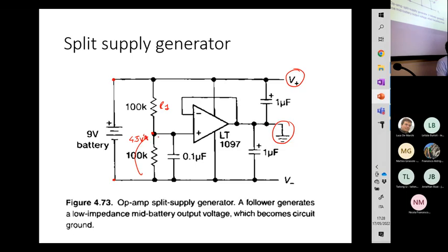Okay. So then we may add a capacitor to achieve a sort of stabilization effect. Okay, so a low pass filtering effect, in order to avoid that irregularities in the voltage here are duplicated at this node.